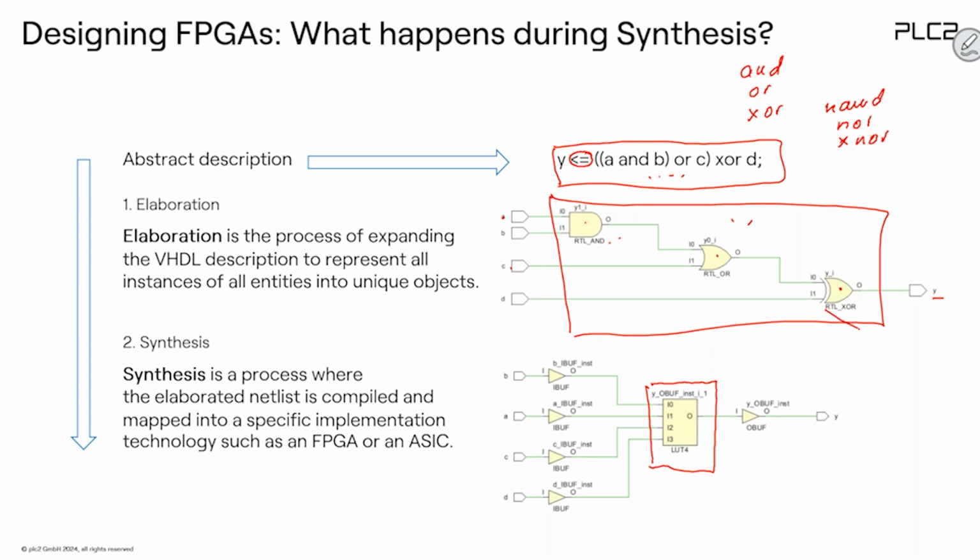So in this case, you know what the synthesis will do. I have maybe the 4 inputs here, and this would be the output Y. So this is A and B and C and D. Because of 4 inputs, there are 16 possible situations here, and then the Y is calculated: 0, 1, 0. So this lookup table is actually implemented right here. This lookup table is nothing else, therefore the name lookup table, than a truth table.